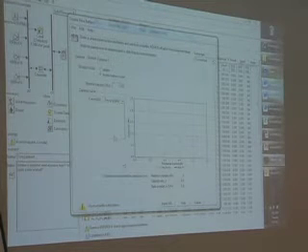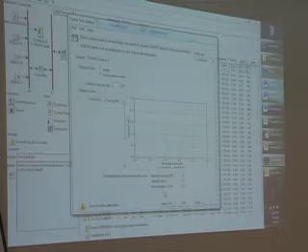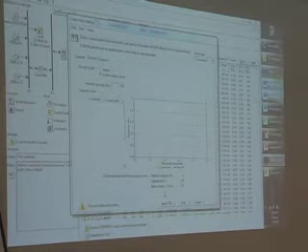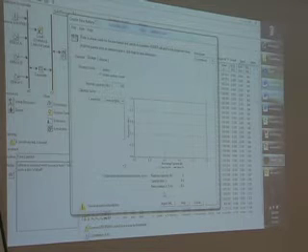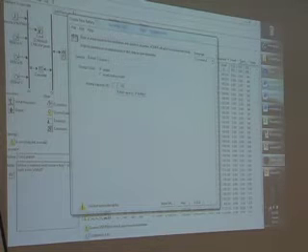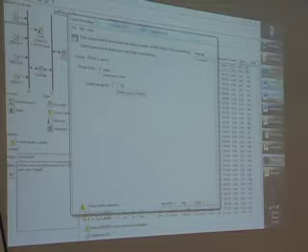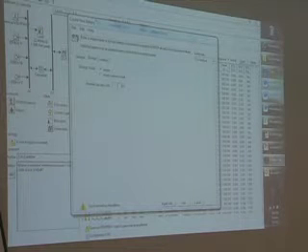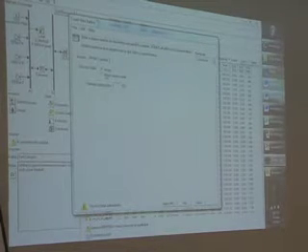You enter that data here, it fills out the graph, and it has this thing in the background called the kinetic battery model, which I could go into detail about, that calculates the parameters for it. If you don't have that data, you can use the simple model, which just says you've got so many kilowatt hours, and that energy is entirely available to you. It's sort of unrealistically favorable to the battery, like an ideal battery. But if you don't have the parameters, that's fine.